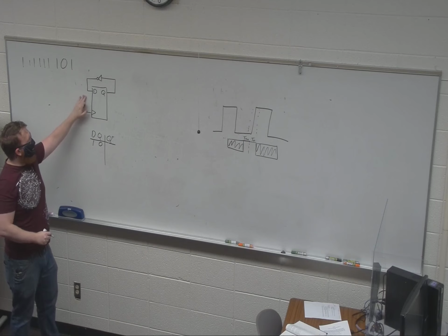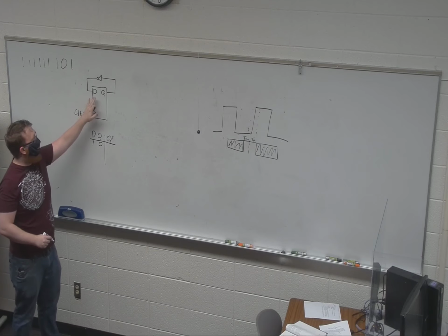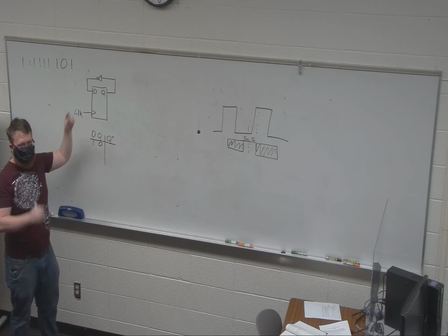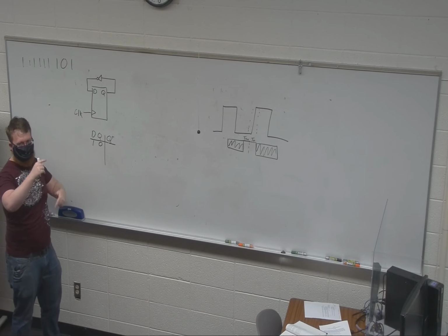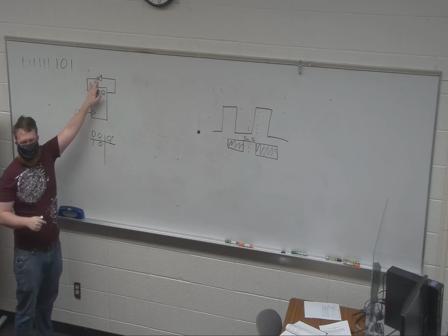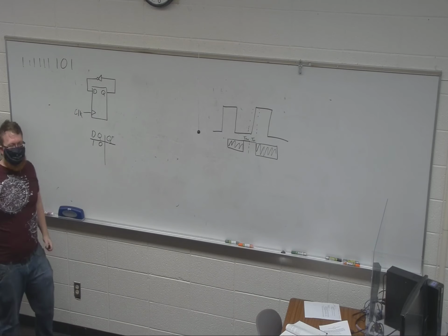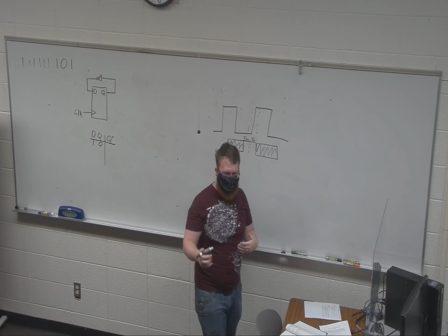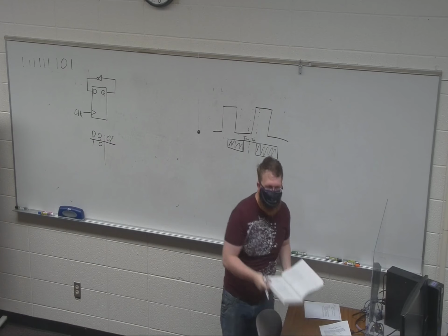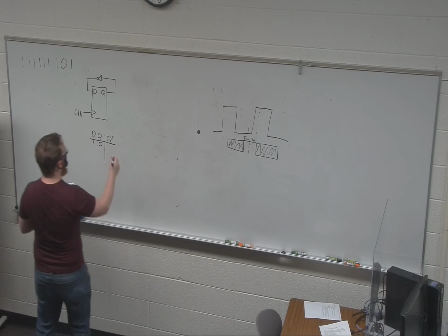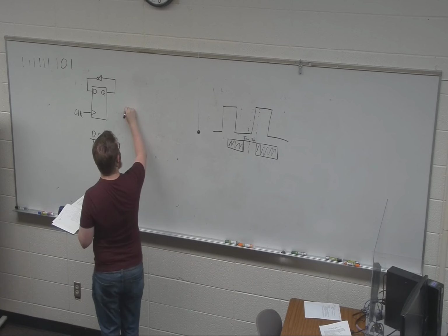And your ideal situation then is that you're going to clock your D into Q, right? And it's just going to alternate 0, 1, 0, 1 as we step through each of this. But this inverter has some delay. So then we're going to start slowly speeding up this system. Imagine that we're starting slow and everything is working fine. We've done our debug, looks great, and then we're like, oh, we have to speed up this clock a little bit.